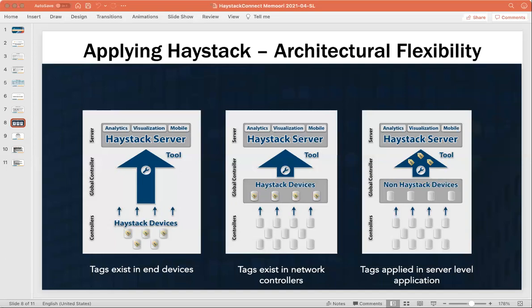Here's why. It's been proven that it lowers the cost, it protects the owner, it creates more uniformity in how these systems are installed, because it forces people to follow a process around how they're going to name their points, how they're going to define what the data is in their system. And so we're recommending it. We're bringing it to the owners who want to build buildings, saying this is a part of the design of your project. You should absolutely be requiring Haystack tagging.